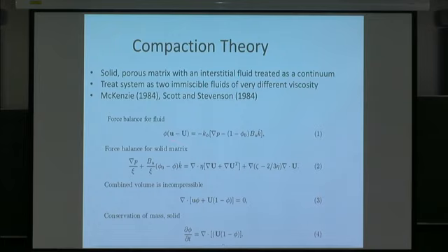So you've got essentially a Darcy law for the separation of the fluid. I've written the fluid velocity as the little u, and the solid matrix velocity as capital U. Okay, you've got a force balance for the solid. So again, I've kept the buoyancy effect here. It's pretty close to a Stokes fluid, but of course there's this bulk viscosity term here.